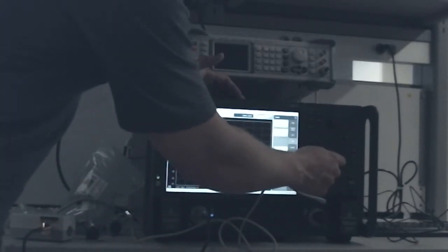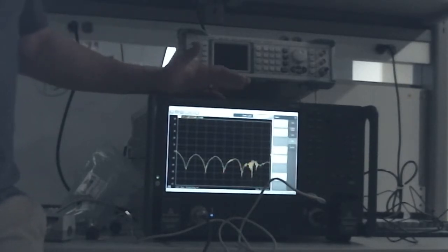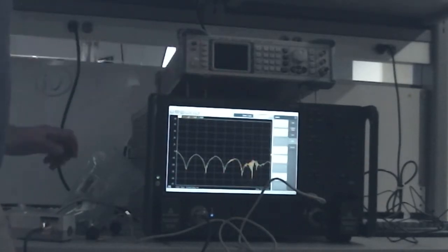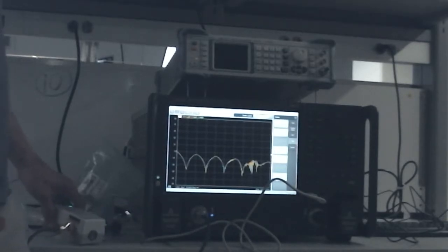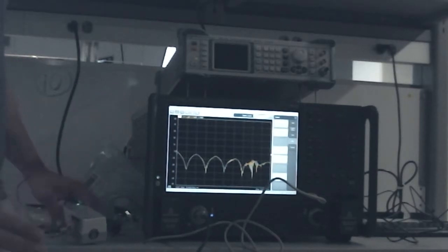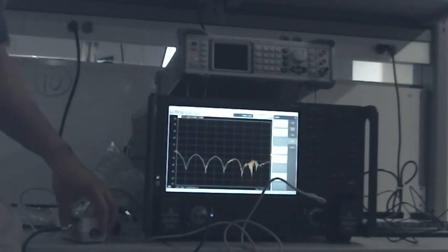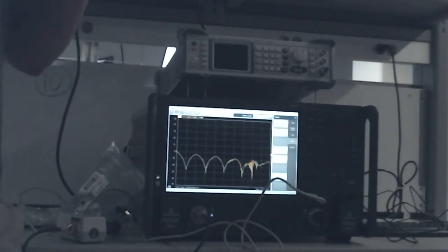But what I typically recommend is that you probably use for passive devices about -5. The reason for that is, -5 to -10 is good. The reason for that is that the eCal typically compresses around -5. So you'll see if you look at this, it says maximum power is plus 10 dBm. That's the damage level. So don't ever put plus 10 dBm or more into the electronic calibration module. You'll damage it. But -5 is sort of where I would recommend that you do your cals. -10, -5, somewhere there.